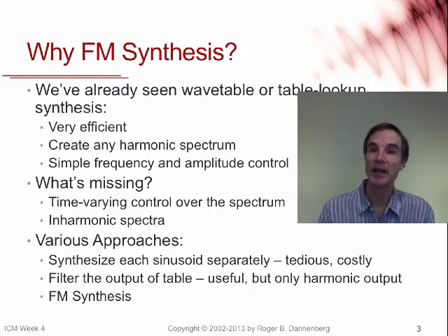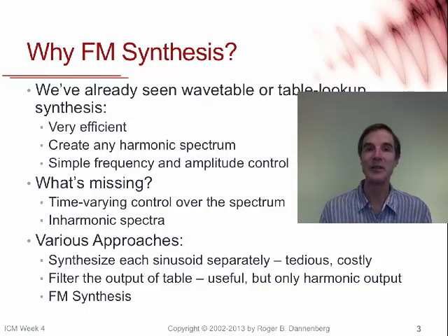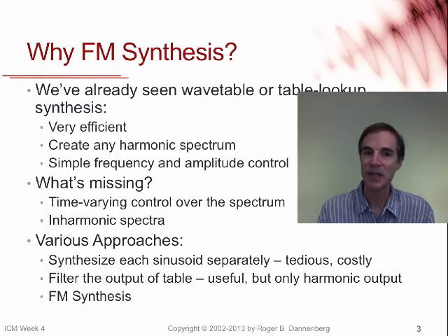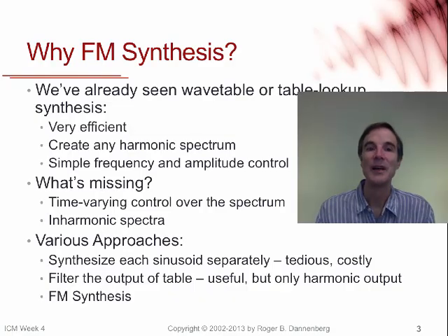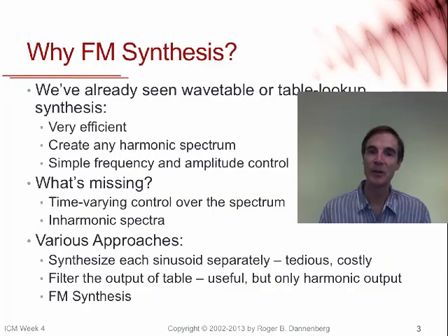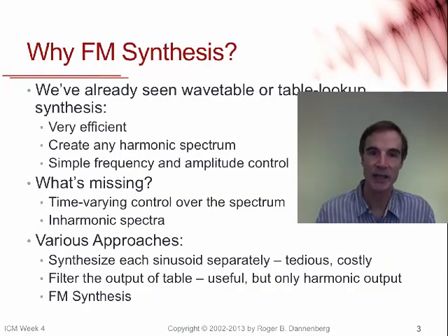I can tell you that that's a very efficient way to make sounds. You can create really any harmonic spectrum by just loading it into a table and playing it. And you have very simple frequency control and amplitude control. So wavetable synthesis or table lookup oscillators is a very practical, reasonable thing to do, but there's something missing, and that is time varying control over the spectrum of the sound.